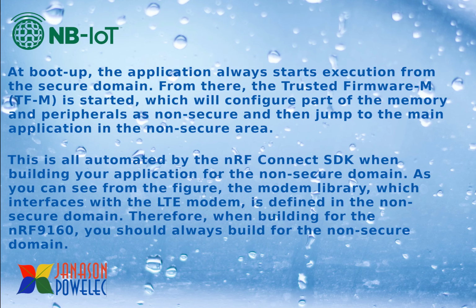At boot up, the application always starts execution from the secure domain. From there, the trusted firmware-M is started, which will configure part of the memory and peripherals as non-secure and then jump to the main application in the non-secure area. This is all automated by the nRF Connect SDK when building your application for the non-secure domain. You can see from the figure that the modem library which interfaces with the LTE modem is defined in the non-secure domain. Therefore, when building for the nRF9160, you should always build for the non-secure domain.